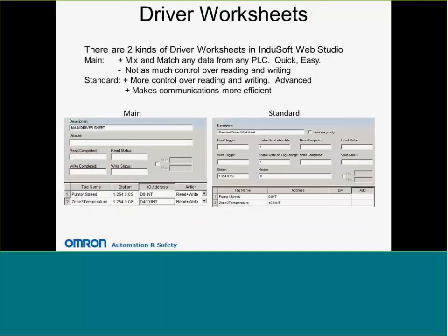I know Scott talked in the beginning of the webinar about driver worksheets, so I'm not going to go into great detail about the differences, but we obviously do support both the main and the standard driver worksheet. My personal view is that I tend to use standard driver worksheets more than the main driver worksheet. It gives you flexibility and control over when reading and writing is enabled. I often do triggering as well. So I'm just showing you a couple of snapshots of what the two look like, and we're going to dive into how you configure both of them within the Omron driver.